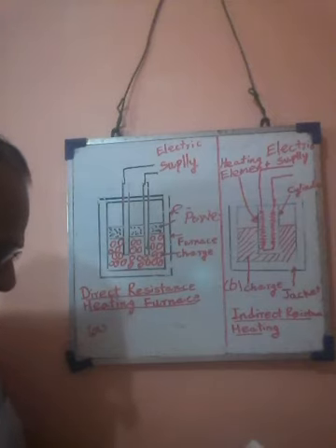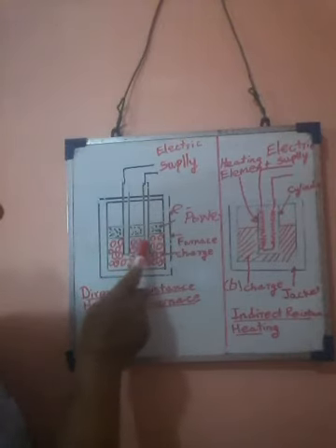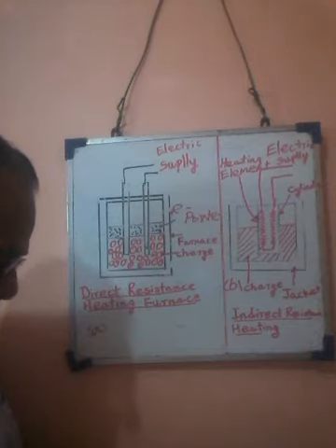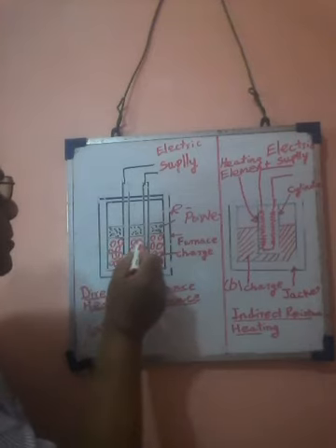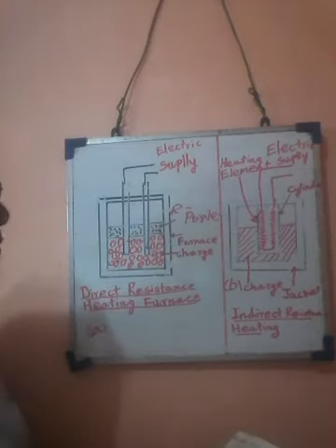When the charge is in the form of small pieces or powder, it is a high resistivity material. Over the surface of the charge, avoid direct short circuit. Heat is produced when the current passes through it, according to the supply frequency, the power frequency when you use 50 hertz.